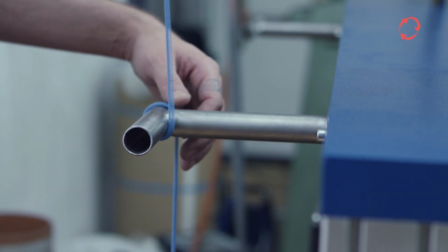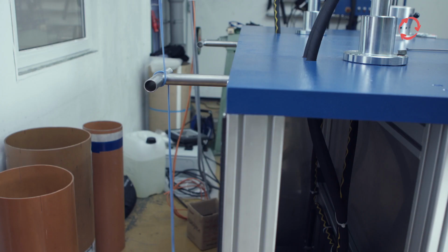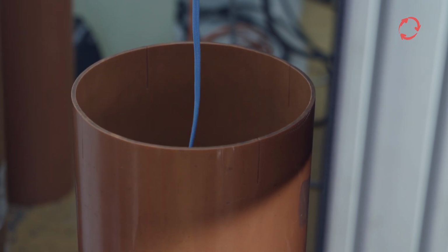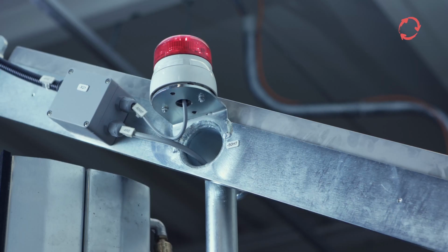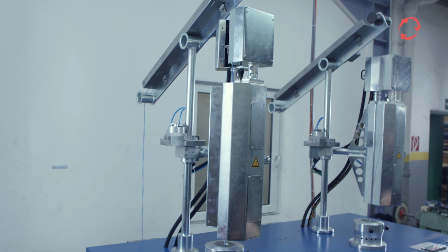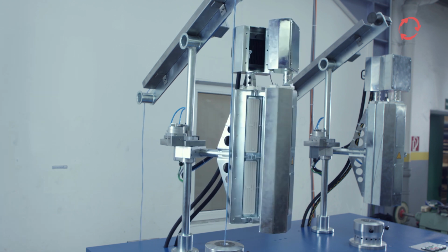At this point, measurements in half-hour intervals are sufficient, and 1-hour intervals if the machine is warmed up. The winding process runs automatically. If a disturbance occurs, for example a thread tear or the coil is empty, the machine will shut off automatically. The red light on the spiral guiding arm will illuminate and an acoustic signal can be activated. When turning the machine off, the heater is automatically opened and then turned into inactive position.